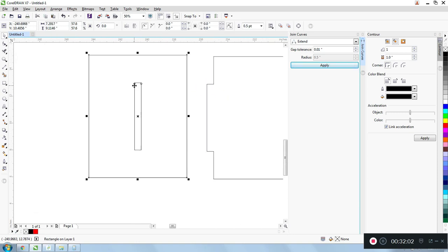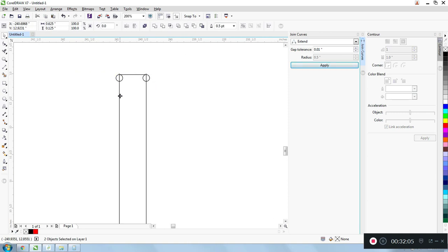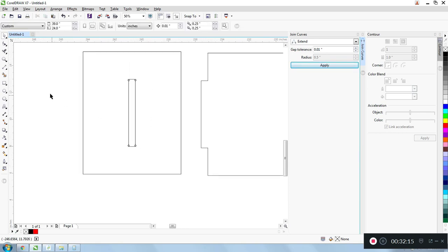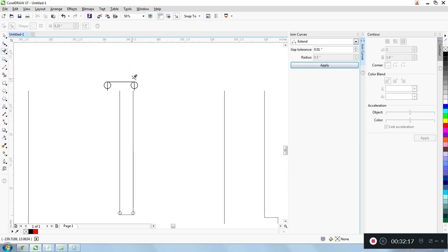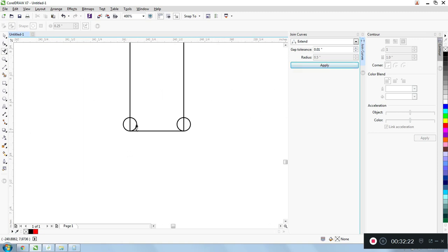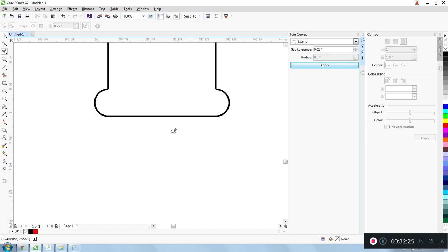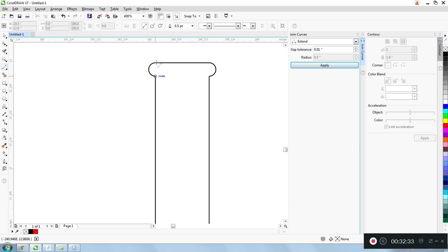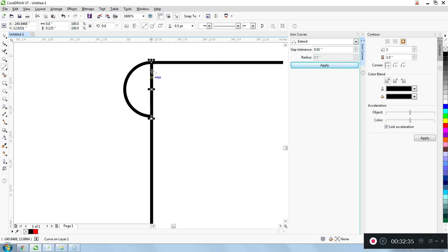And then I grab these two and I snap them to the bottom of the object, and I'm grabbing it, dragging it, and then right clicking so I duplicate it. And then I just get rid of all of these lines in the middle, and now we have a dogbone slot. That means that this inner corner is actually capable of accepting a piece with 90-degree corners.